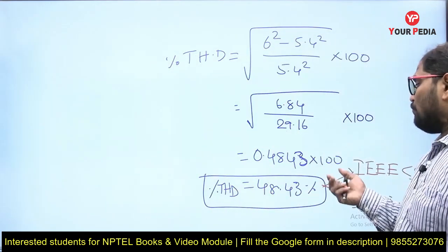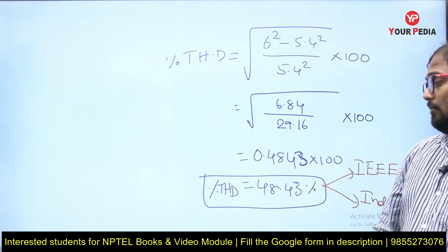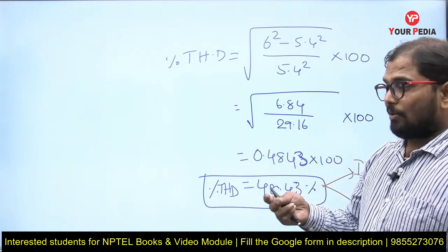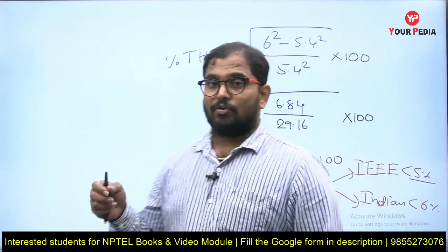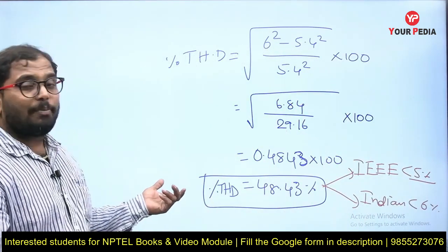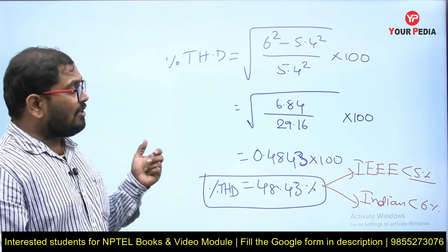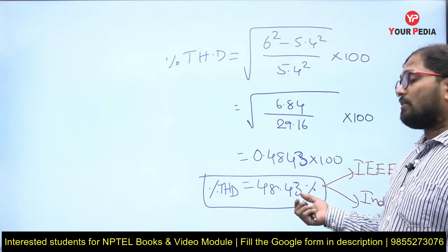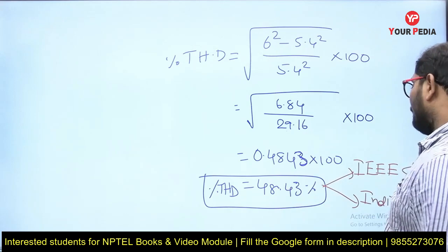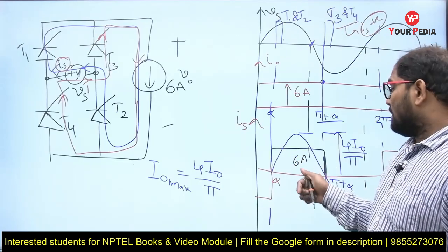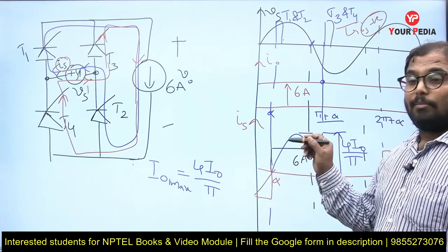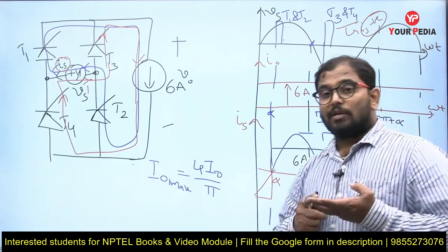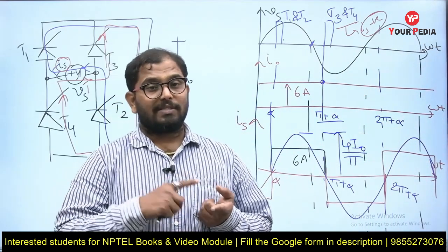You got this kind of waveform because of the presence of a square waveform in the current. So to avoid this, we will go with filters. THD, total harmonic distortion, is producing harmonics in the existing circuit, which will reduce the performance of our converter. If you observe the current waveform, it is not sinusoidal; this square waveform has different harmonic components. The fundamental it will have, third harmonic, fifth harmonic, seventh harmonic.